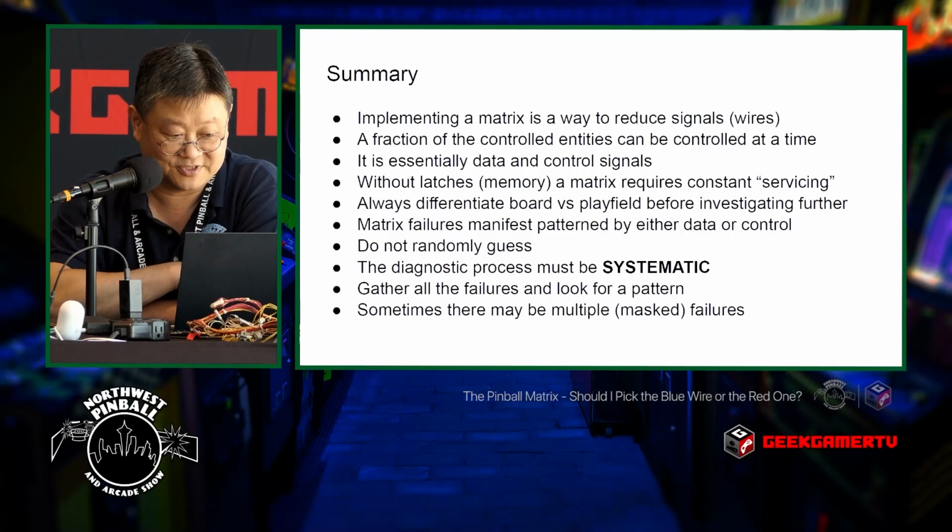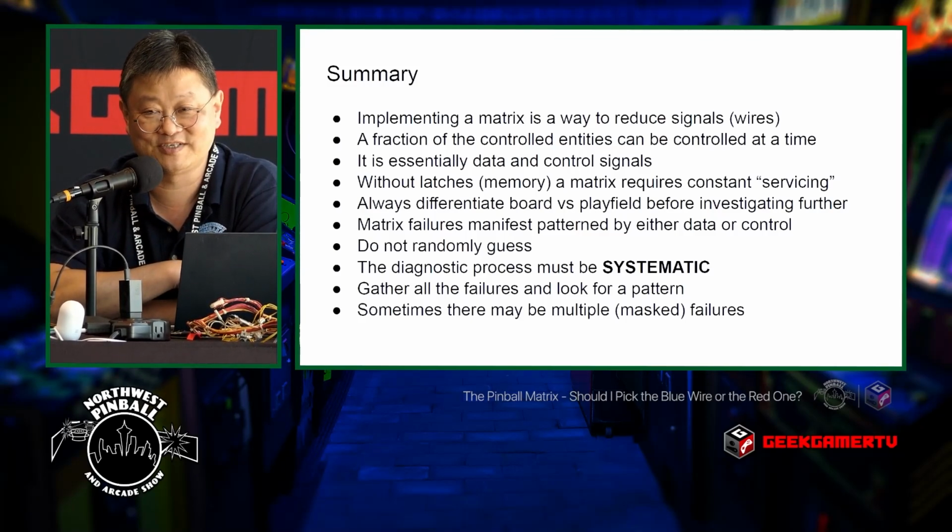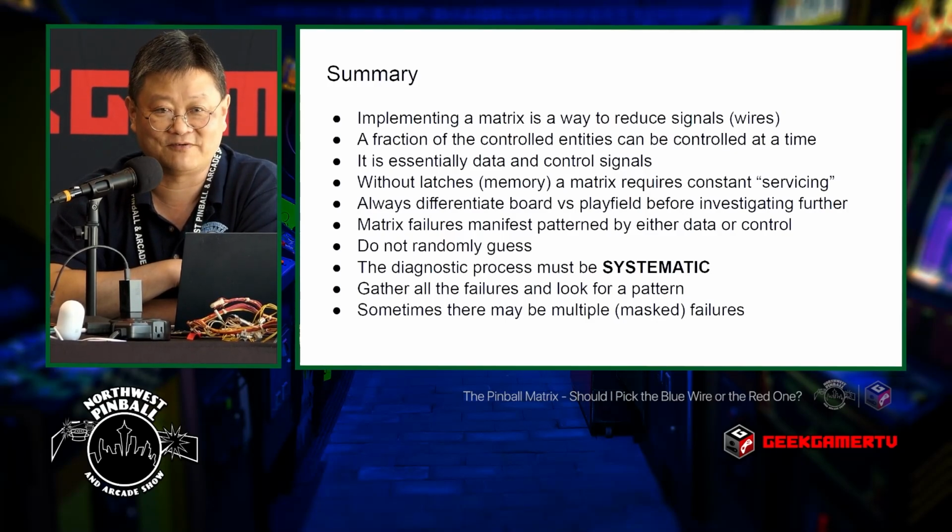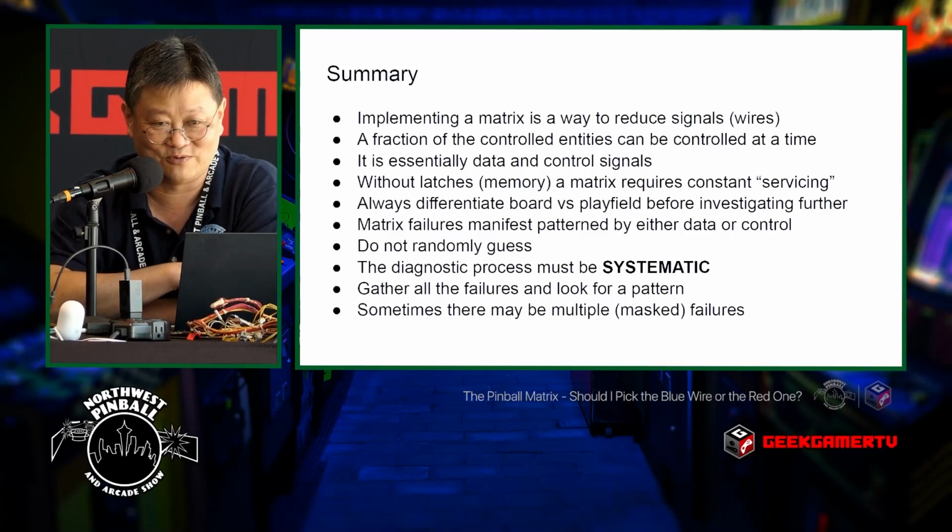The diagnostic: do not guess randomly. Diagnostics must be systematic. You oftentimes see people say, well, go to the switch matrix chart, figure out, write down which switches work, which ones don't, and people often look at that and say, oh, that's too much work, I just want the answer. It doesn't work like that. The matrix by its nature is complicated, which means you have to invest some work in it. And if you don't want to invest the work, that's okay. Ask somebody to come out and pay them for their time. Otherwise, learn how to do it yourself.